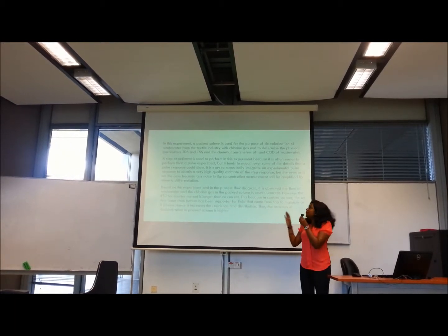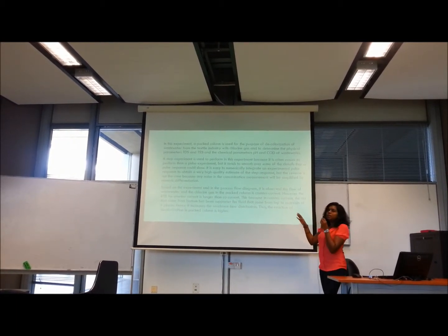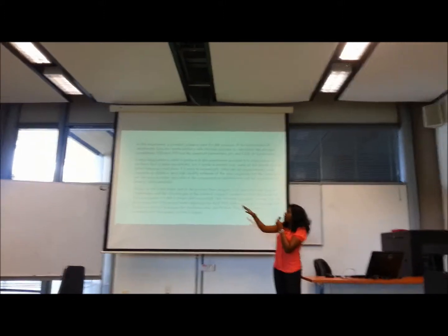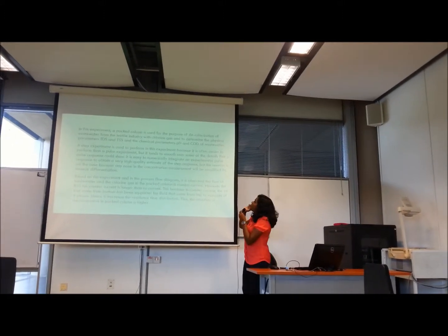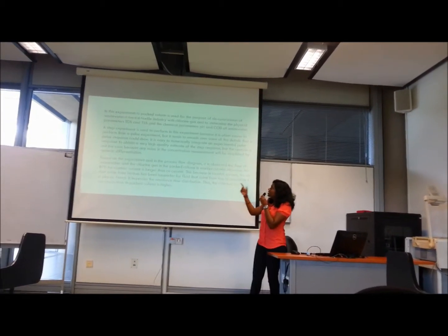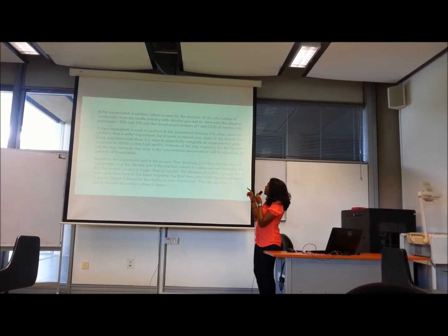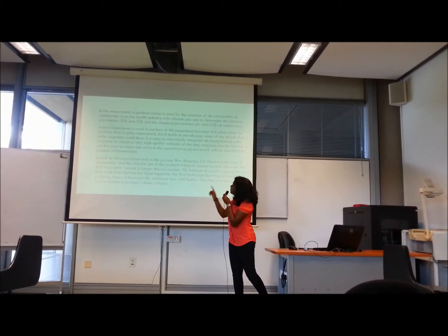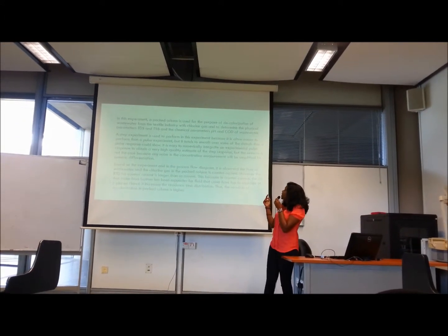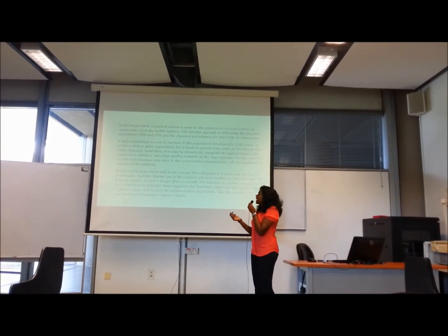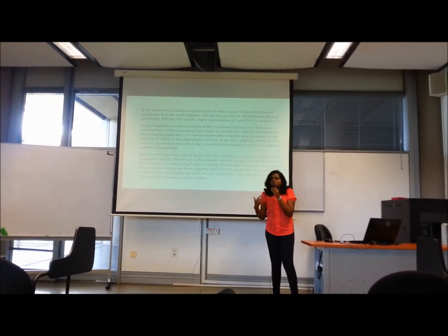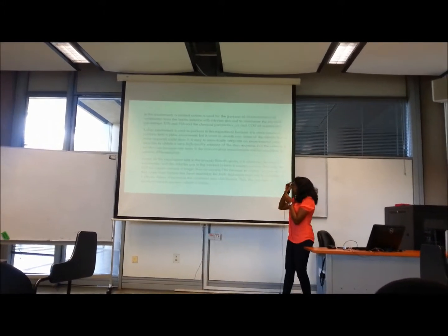A step experiment is used in this experiment setup because it is easier to perform than a pulse experiment, and it tends to smooth over some of the details that the pulse response could show. It is easy to numerically integrate an experimental pulse response to obtain a very high quality estimate of the step response. But the reverse is not the case, because any noise in the concentration measurement will be amplified by numeric differentiation.